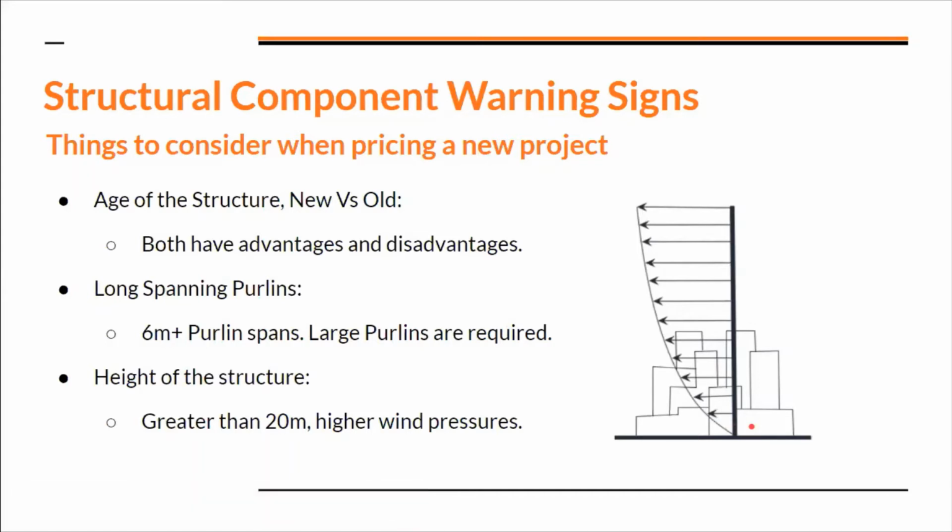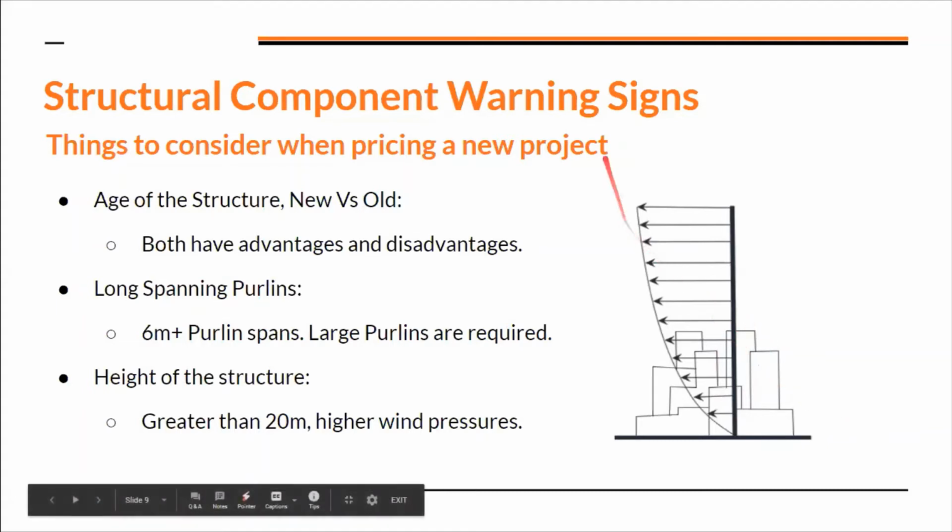If you're in a tall building or on a balcony, obviously there's a lot more wind than when you're down on the floor. In the same respect, if you've got solar panels higher on top of a skyscraper, or even a 10-story or 5-story building, it's going to be very different to your residential style or your standard 4-meter warehouse height. So take that into account. There is a maximum wind speed at one point, but it does increase significantly in the initial 20 or so meters.